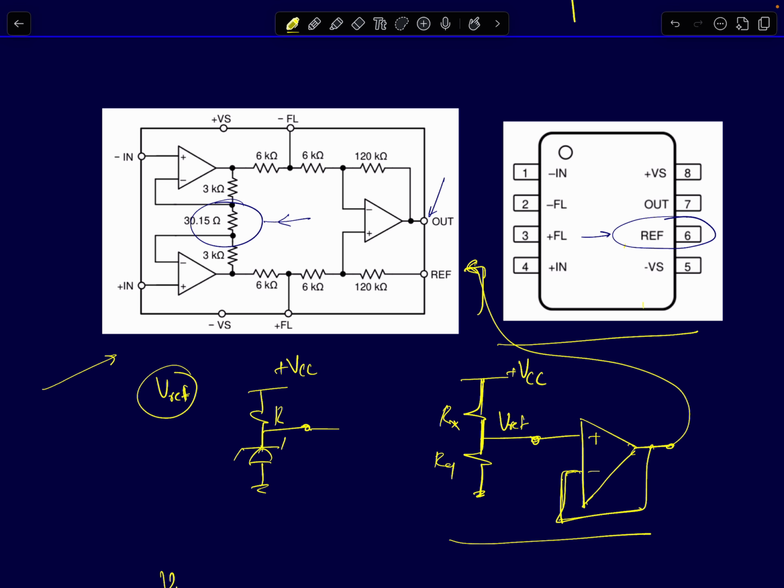Now if you observe this instrumentation amplifier chip, we have so far accounted for how many pins? There are 2 input signals, so 2 pins are going to go for that. 1 output signal, so 3 pins have gone there. Then you will need supply pins, supply and ground pins, or for bipolar supply you will have positive and negative supplies. So that will take up 2 more pins. So that covers how many? 1, 2, 3, 4, 5 pins. Now we included the reference pin, 6 pins. So totally all the 6 pins are now covered.